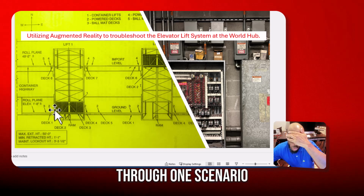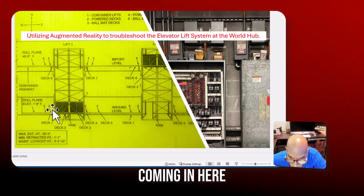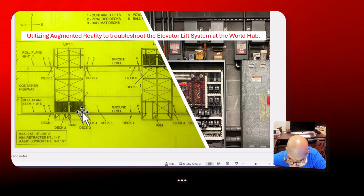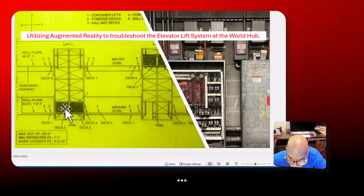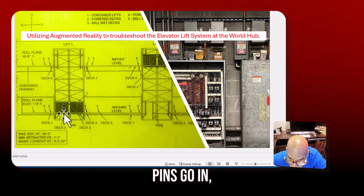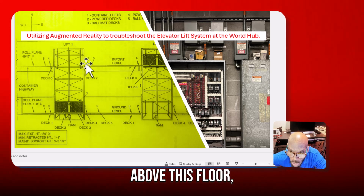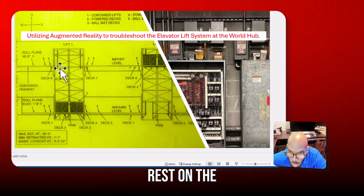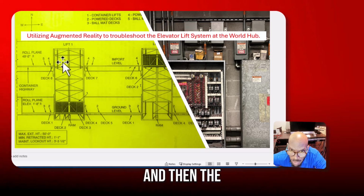So let's go through one scenario where a container is coming in. A container comes in here. Then the bar stops come up, the doors close, the lift raises up, and the pins go in, and then the lift goes all the way up. Once it gets above this floor, the pins come out, then the lift comes down and rests on the pads up there. Then the doors open, and then the containers come out.